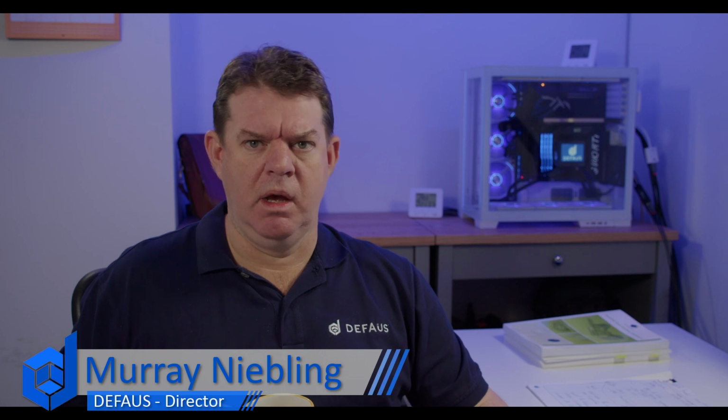This morning's episode I would like to discuss standalone beams and how they are different to standalone purlins. I recently had a project where we had a beam that was to be site welded. Now it was a beam that didn't have any attached parts, so it wasn't allocated an assembly drawing, although it is allocated an assembly number, but there will be no assembly drawing created. It's a standalone single part that is site welded.